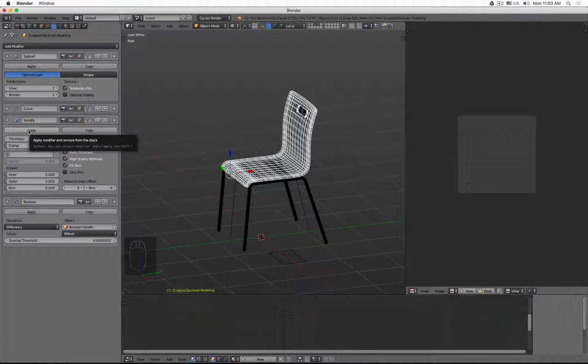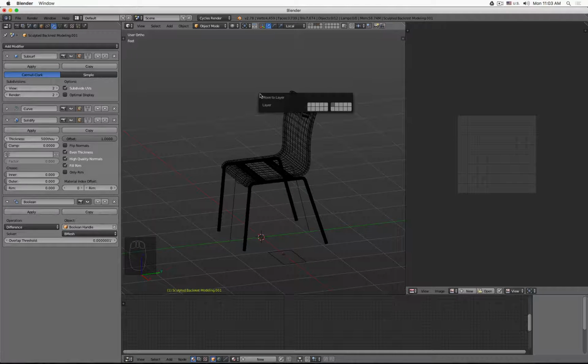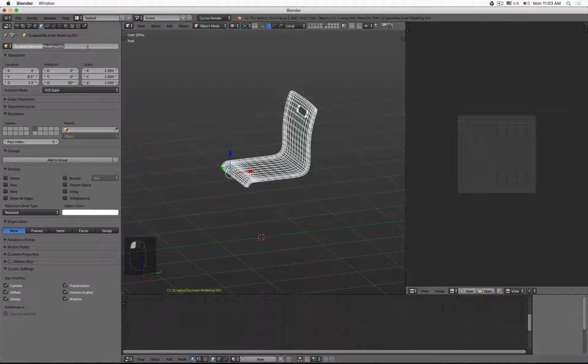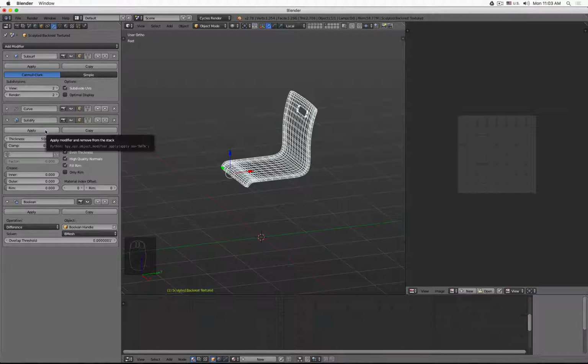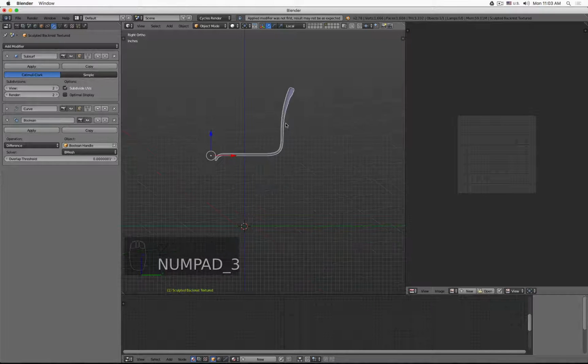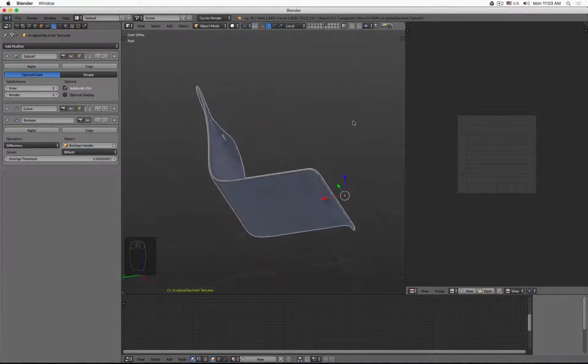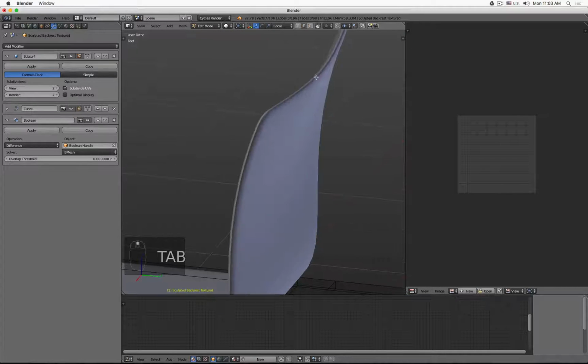So you can either apply the solidify modifier later if we want to add one, it's not going to be too much, or we simply make a copy of this one, M and maybe 6, so it's further away, and this one, for example, we call textured, and the solidify modifier I will apply. Okay, good.